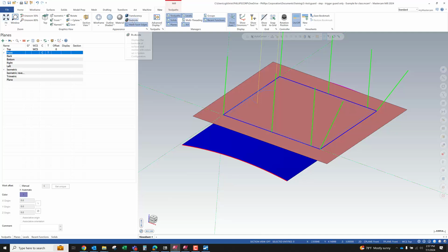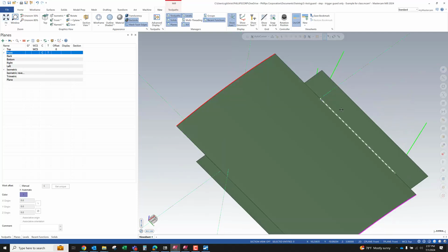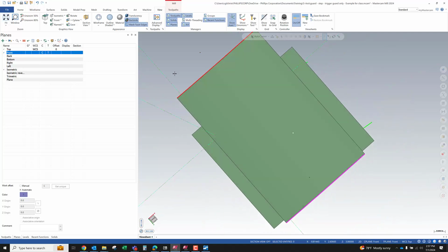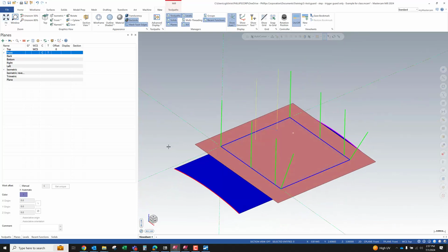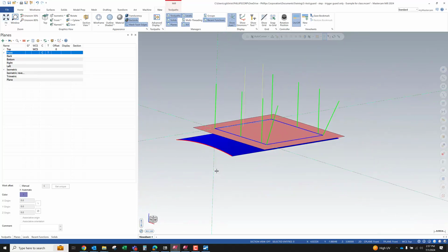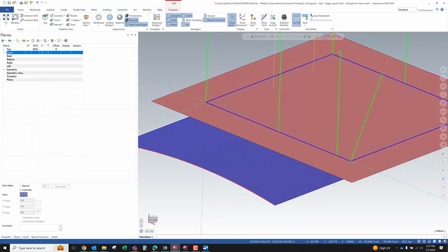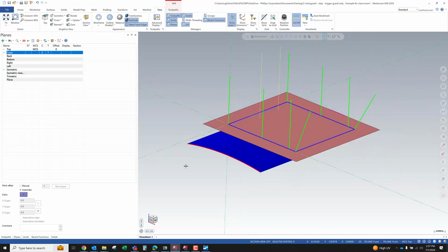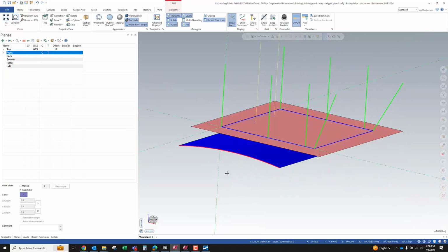So I like to turn on backside, and when I do that, this olive green color, not quite olive drab, is the backside surface color. So that way you can instantly visually see which side on the surface is positive and which side is the backside. So the surface normal is always the positive side of the surface. One other thing that's true